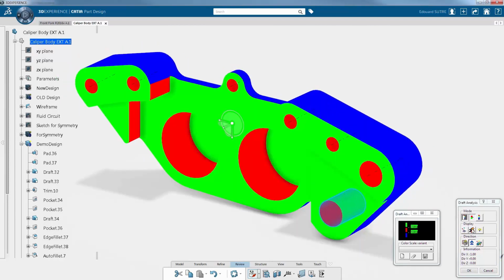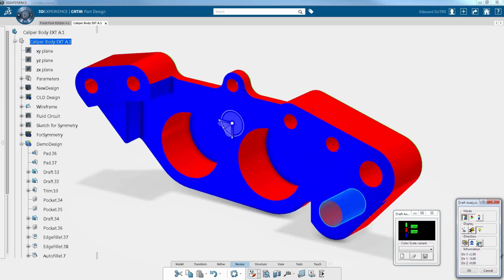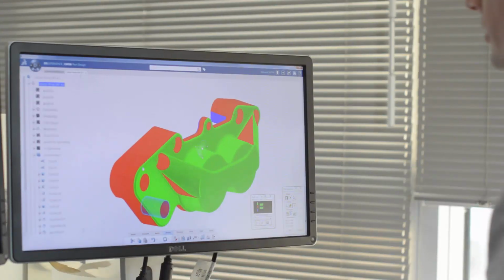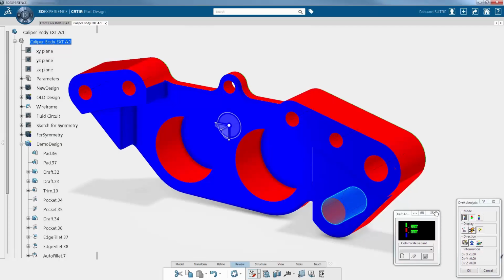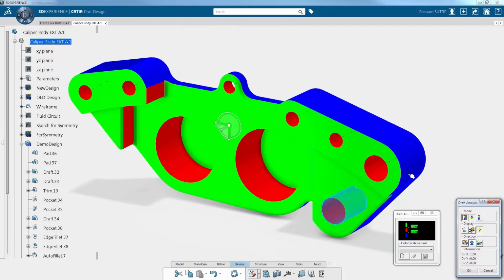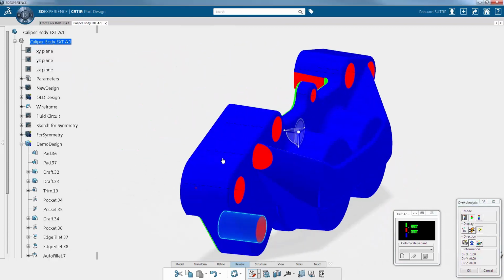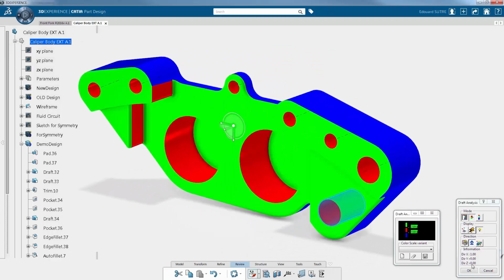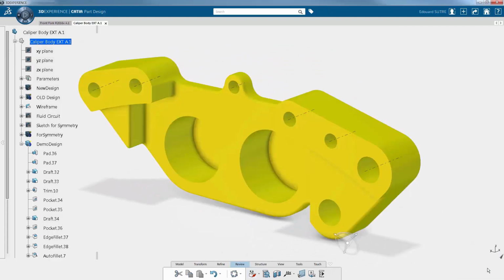When it concerns the inner part of a hole, it happens to be irrelevant since other machining processes will be involved later on. You can manipulate the robot to make sure that each 3D element can be unmolded from the interior and the exterior. It is important to notice that the part is colored in blue all around the part. However, if there was a small place colored in red, it would mean that one side will get trapped.